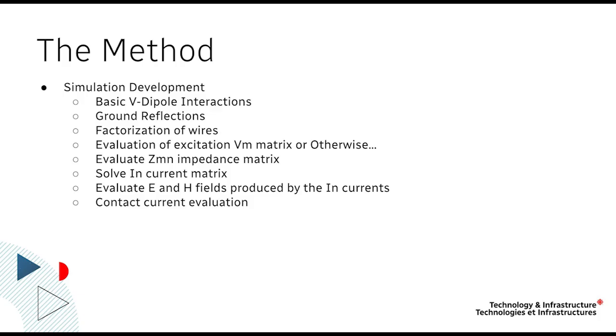Once you have that, you pass those dipoles to the impedance matrix calculator, which will define the interactions between all the parts of your system. Let's say that there's no excitation and that it's just the tower, the guy, no antenna is involved yet. And then we calculate the excitation with the antenna that it has on every piece of the environment. And then we get the excitation vector.